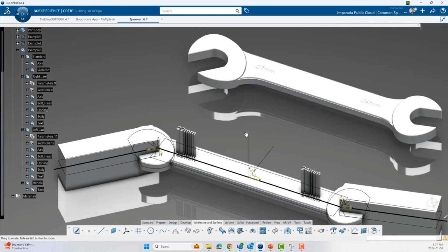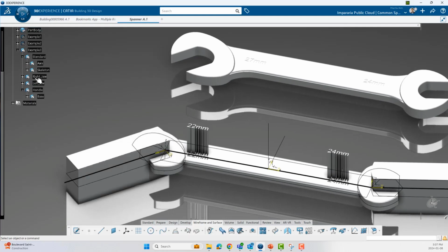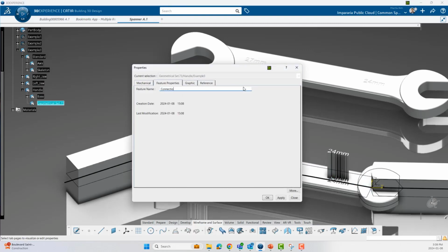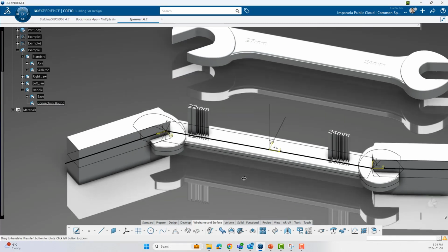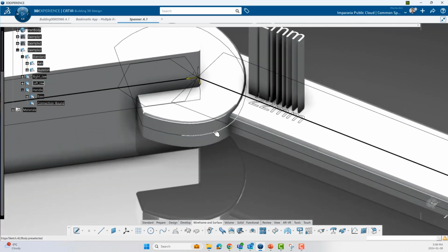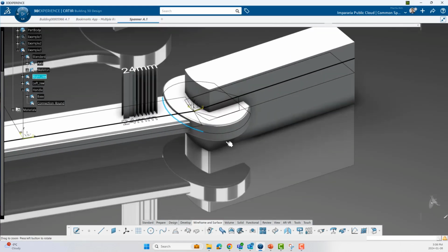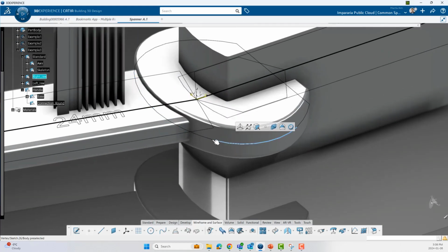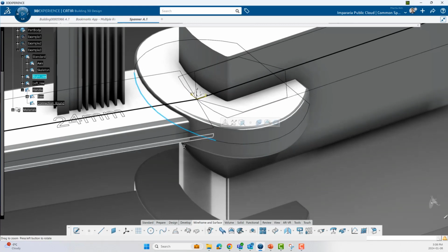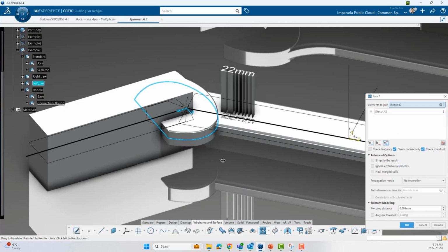Then let's create the connection arc. So this is another challenge. So we now have three, and we are here creating the connection. Let's use this sketch and this sketch. But when people rotate, you don't want to ever get an error. So this line and this line should be treated as one line. So what we can do is we use the join and we click this join.